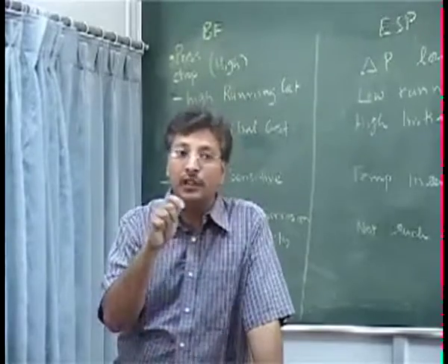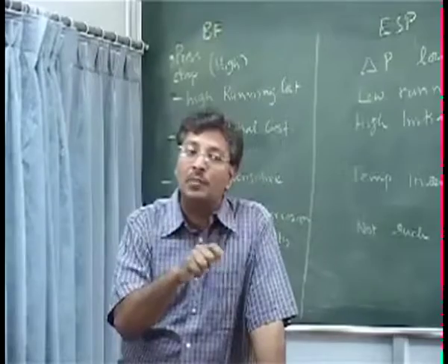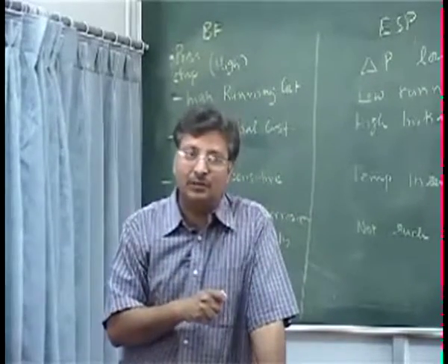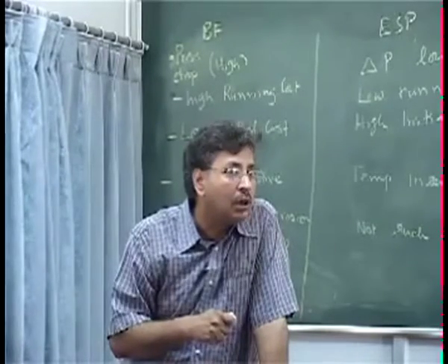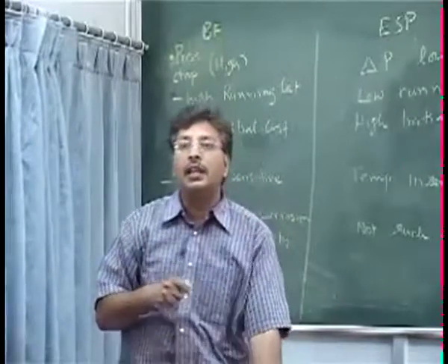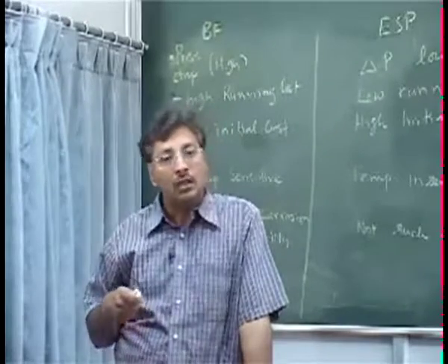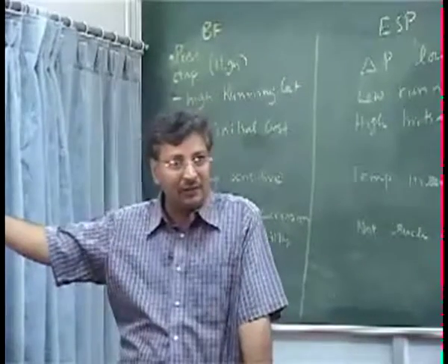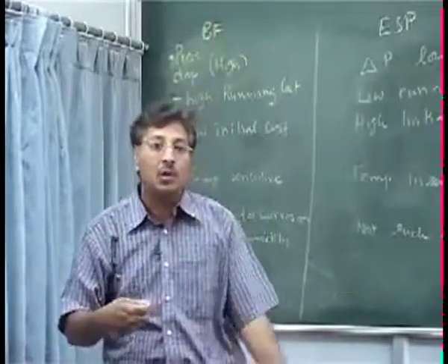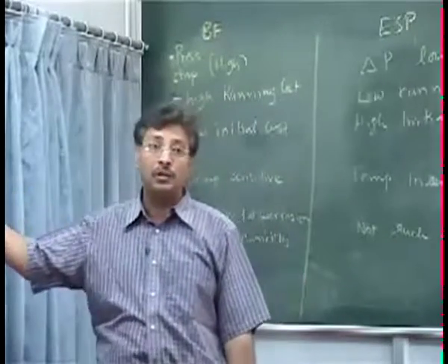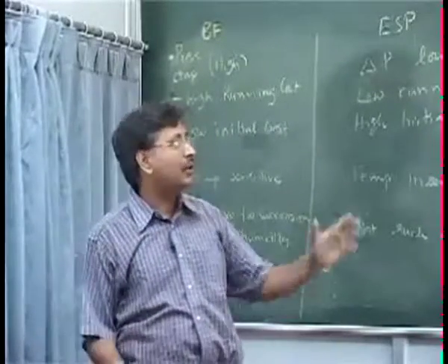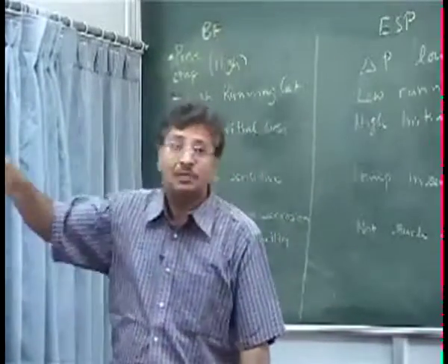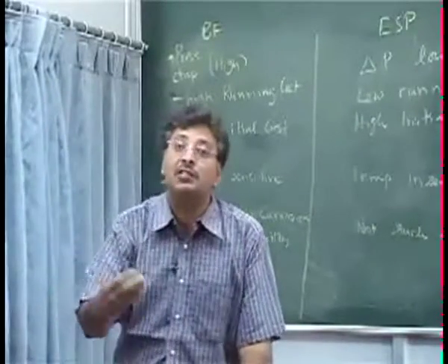The gases may contain water, but it is in the vapor form, and the SO2 will not be in the form of sulfuric acid, it will be in the form of SO2. And for SO2 to convert into H2SO4 is very difficult. Not H2SO4, sir. Water depositing on the metallic plates, and their corrosion may occur. See, but then again, corrosion needs just oxygen and water. Yeah, the corrosion occurs, but then again, consider the size of the plate you are talking about, versus the corrosion that makes a hole in the fabric filter. Problems will happen, but in the long term the huge steel plate will last, compared to the fabric, in the relative sense, with some slow corrosion going on. Again, there will be a cake, and we stop the corrosion by painting, and the cake itself will act as a resistance to corrosion.